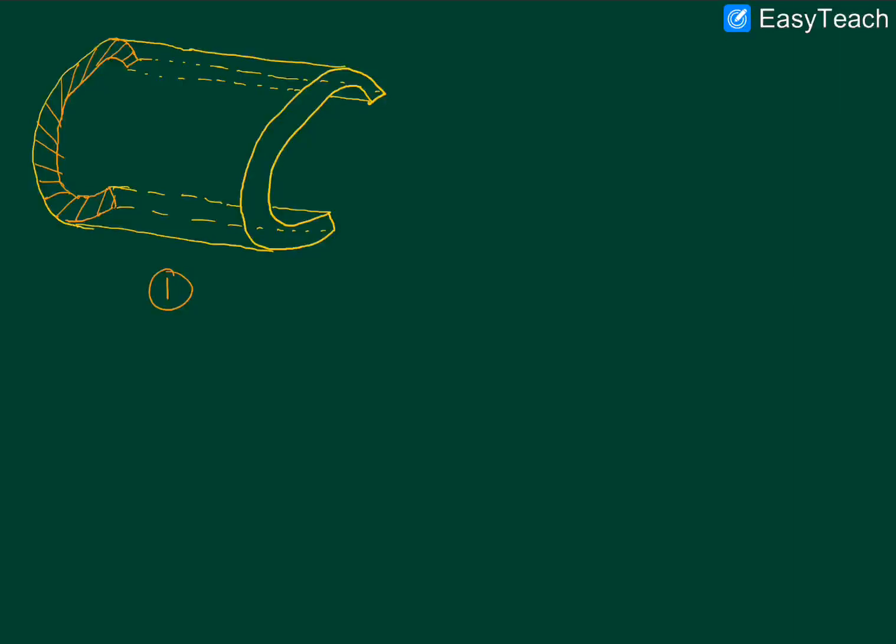Okay. Let us not forget that we have our transverse force acting like this. All right. So I repeat again that it is the distribution of shear stresses which is present over this hatched part which will contribute to a torsional moment which will exactly balance the torsional moment that is contributed by this transverse externally applied force when we take the moment about the axis, and that axis would be this x-axis.